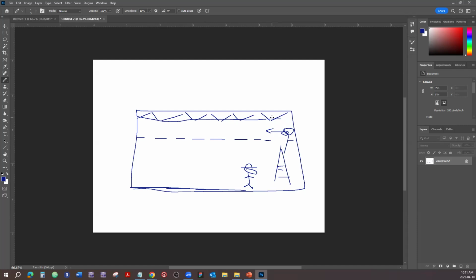So you tie the string on one side, tie the string to the other side, and then you're going to have the string coming down to the floor. Here you can tie the wires to the string, do that nose prep thing, pull that on the other side. So it takes two people, one person feeding the wires into the ceiling space and the other person pulling the string with the wires later. With one person, quite often it's difficult to do because any obstacle, any right angle, anything that the wire is going to be rubbing onto, is going to produce friction, and they're going to basically give you opposition to the wire pulling.